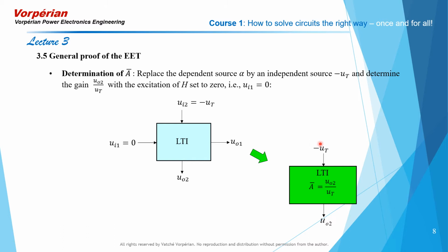What you really are doing is you are figuring out how much does an independent excitation at the point where the dependent excitation is talk back to the value on which the dependent generator depends. This is the talk back from the point where the dependent generator is, using an independent generator to see how much it talks back to the variable on which it depends. It's an inverse. That's why we call it an inverse gain.